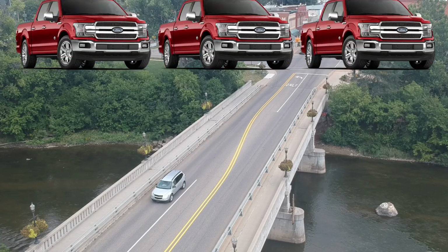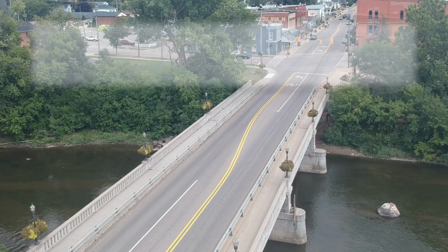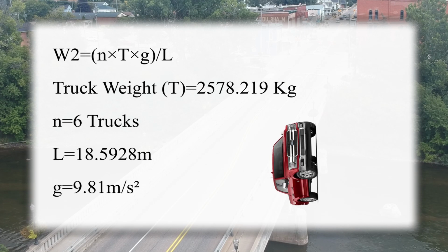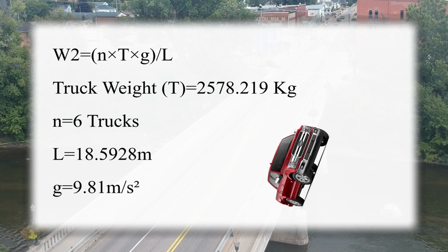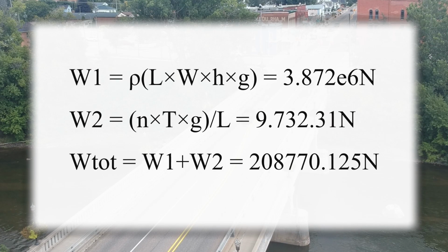We used 6 crew cab F-150 work trucks to simulate the most weight the bridge will have to hold based on traffic in the area. The equation used for the force is W2 equals the number of trucks times the mass of a single truck times gravity divided by the length of a bridge section. We then added the forces together to get W total for the bridge.